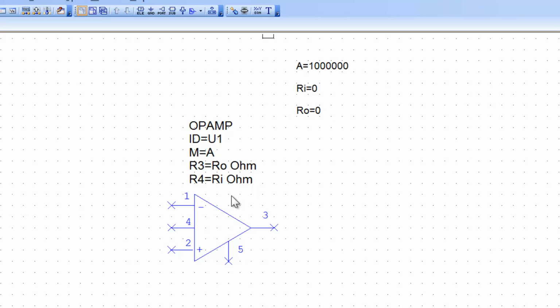So now we are almost there. We've got pin 4 that we can completely ignore. Pin 1 is our inverting input, V-, pin 2 is our non-inverting input, V+, pin 3 is our output, and pin 5 is our reference, which often enough will just be ground. So we need to specify the ground reference for an ideal model of an op-amp, because you don't have the voltage rails connected. And this is an issue because when you have voltage rails connected to an op-amp, the ground level is the middle point between those two voltage rails, and we will have seen this in the lectures.